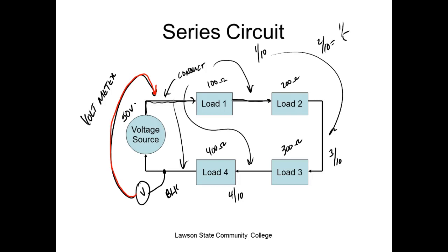When your engine's running, lead acid batteries have more voltage put on them than they're rated at, around 14.3, right around there if the car is running. And then as soon as you turn it off, it'll probably drop down to around 13 volts. And if you let it sit overnight, it's going to measure about 12. So right now, if I put my voltmeter across this, I would measure 12 volts.